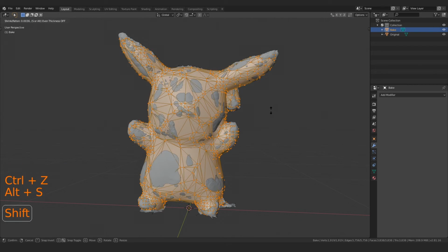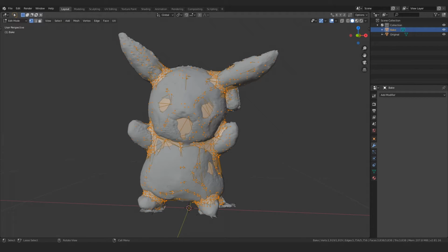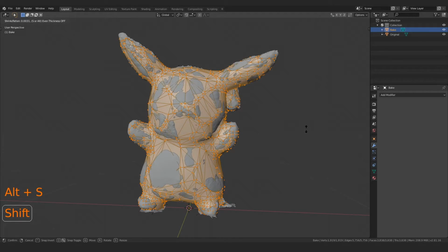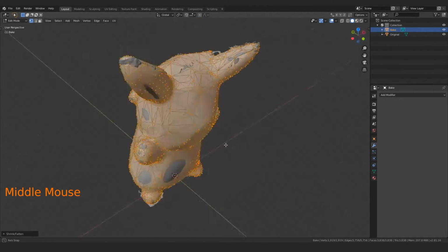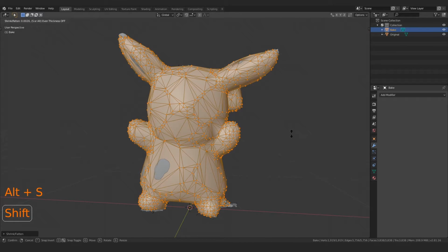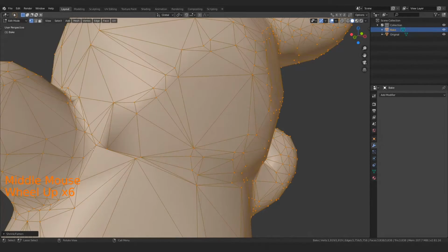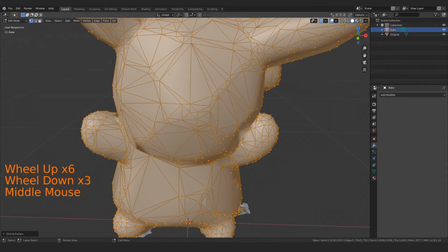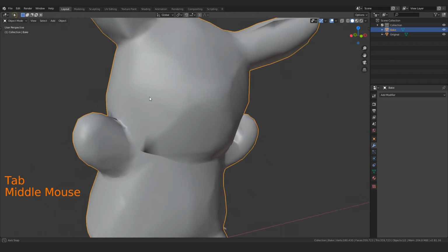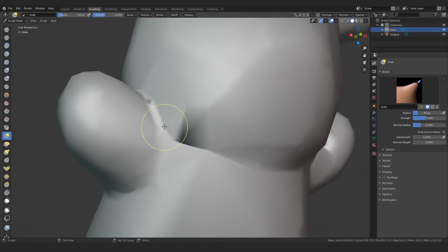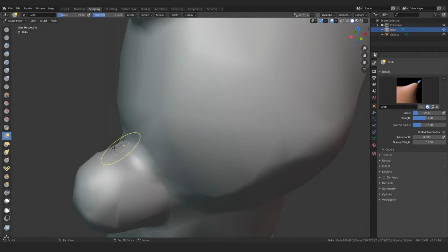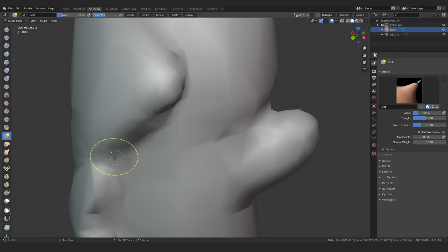So be very careful, because in some places like here near the neck and the arms, we don't want them to interpenetrate on themselves. We just want to inflate out just enough so that it encompasses the model like that. I can see there's a little interpenetration going on, so I'm going to hit the tab key, go into sculpting, and take a smaller brush and smooth some of that out so that it's not penetrating in on itself, but it's also not showing any of the model through.